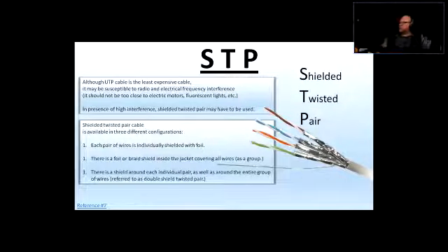Now, the shielded twisted pair cable is available in different configurations. I just listed three. Okay, so let's say scenario number 1. All right, each pair of wires is individually shielded with a foil, just like here. Each pair has its own shielding. And over here is something that's called a drain wire or a ground wire, and that actually has to be connected to a ground.